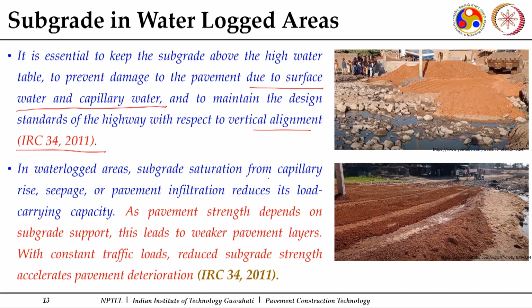In waterlogged areas, subgrade saturation from capillary rise, seepage or pavement infiltration reduces its load carrying capacity. As pavement strength depends upon the subgrade support, this leads to weaker pavement layers, and with constant traffic and reduced subgrade strength, it accelerates the pavement deterioration.